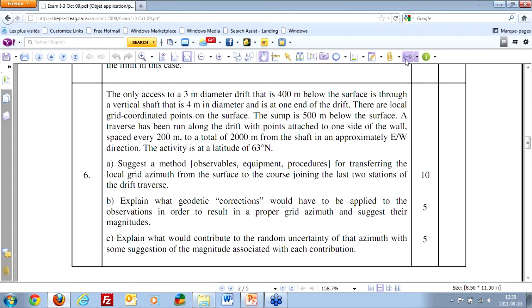So if we then combine that, so that would be 0.43 divided by 2 squared plus 0.25 times 2 squared plus the 0.2 squared, combine them all together and we get an uncertainty of 0.57 of a millimeter for each individual wire. And if we take and have the wires, say, 0.25 in from each side, that means that they're 3.5 meters apart. We have the 0.57 at each one, square the 0.57, double it,